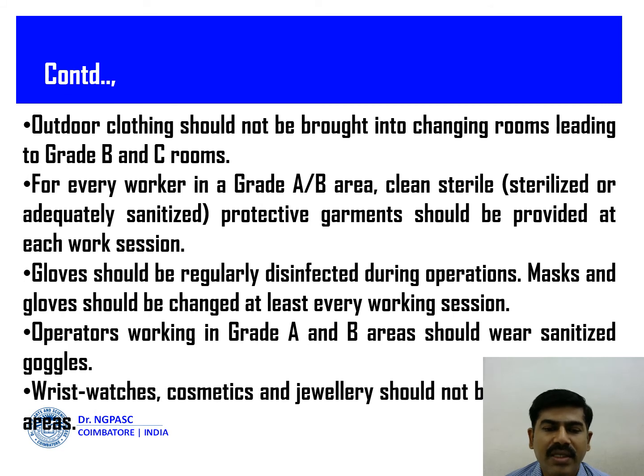Outdoor clothing should not be brought into changing rooms leading to grade B and C rooms. For every worker in a grade A or B area, clean, sterile, protective garments should be provided at each work session. Gloves should be regularly disinfected during operations. Masks and gloves should be changed at least every working session. Operators working in a grade A and B area should wear sanitized goggles. Wristwatches, cosmetics, and other ornamental jewelry should not be allowed in these critical areas.